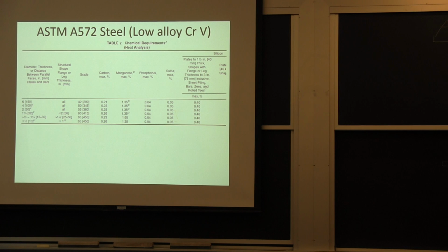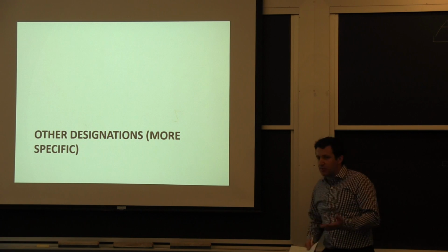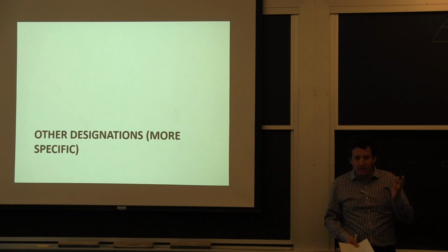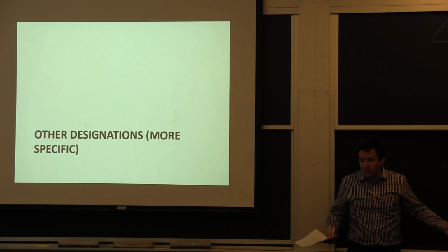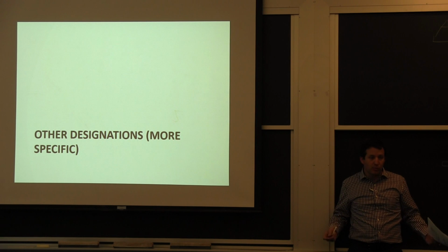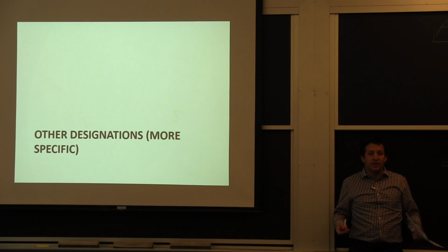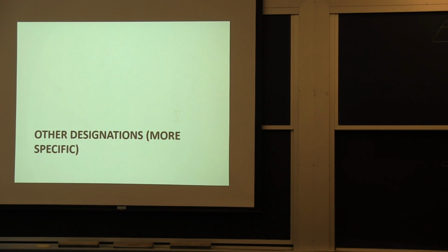Yeah, we covered this. So the basic spec for material, obviously, is chemistry. In steel, you have to worry about impurities. In aluminum alloy, depending what you're looking for. If you're looking for electrical conductivity, you want extra pure. Otherwise, a lot of times you're looking to put alloying element to increase your properties, because aluminum is so soft.